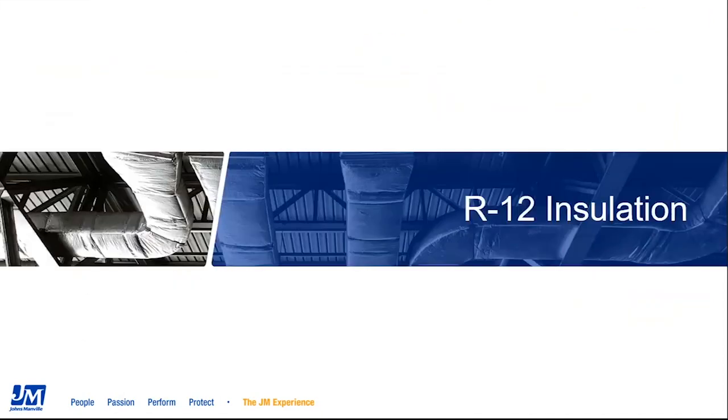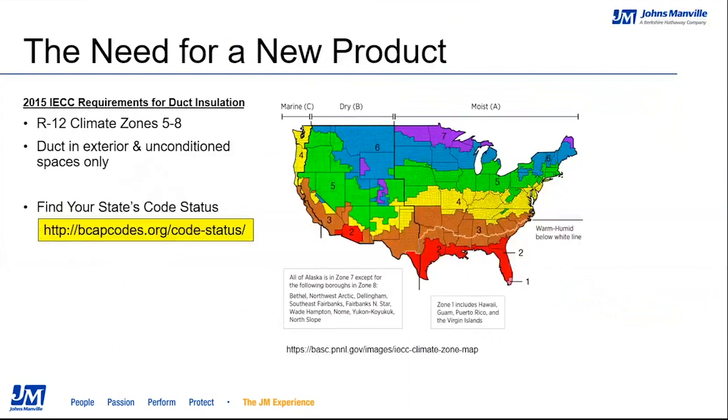R-12 insulation, the need for a new product. Where should I be using flexible R-12 duct insulation? First, it depends on where you're located on the climate zone map. If you look at the Mason-Dixon line on this map, north of that gets you to climate zones 5 through 8. And in climate zones 5 through 8, there's a requirement that R-12 insulation be utilized on ducts in exterior and unconditioned spaces.